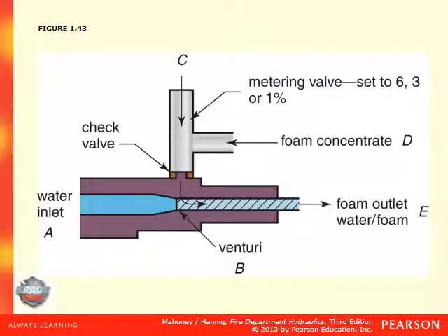Okay, so the reason they want you to know about Bernoulli's principle and the wing being similar is the fact that in firefighting, sometimes we use what is known as a foam inductor. And the foam inductor operates off of Venturi principle, where foam concentrate, the line going to, say, our foam bucket, is drawn in to the line here to be administered and put on fire to help put it out, whether it be a chemical fire or a woods fire. You have a valve here that'll set it to what percent you want, usually 6 to 3%.